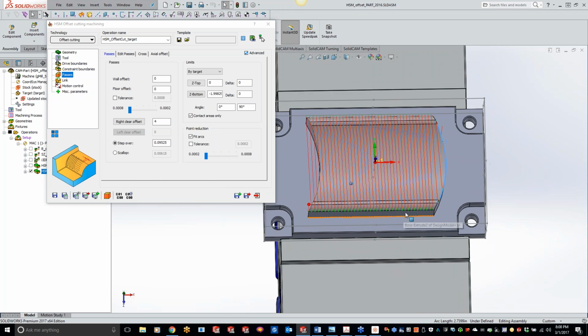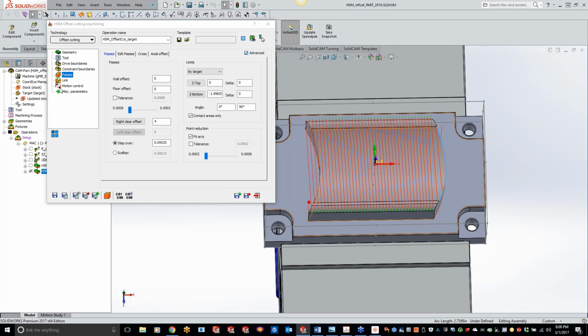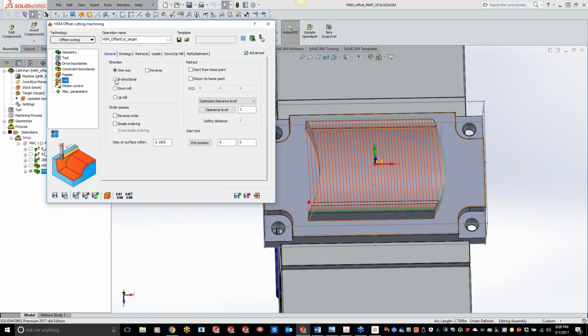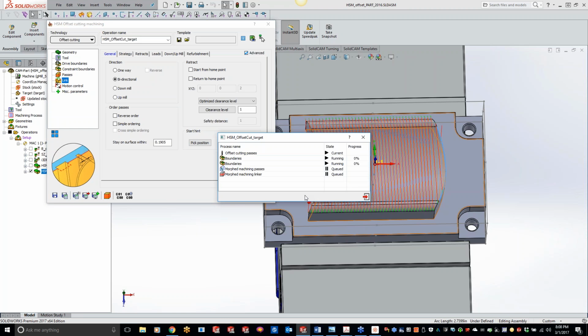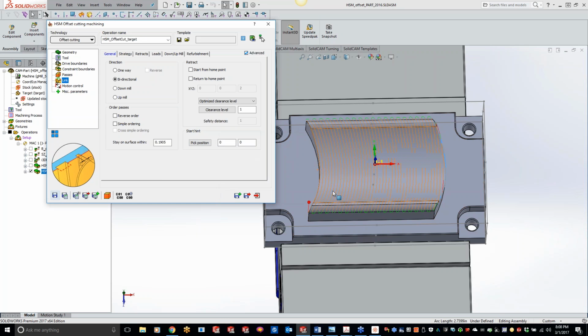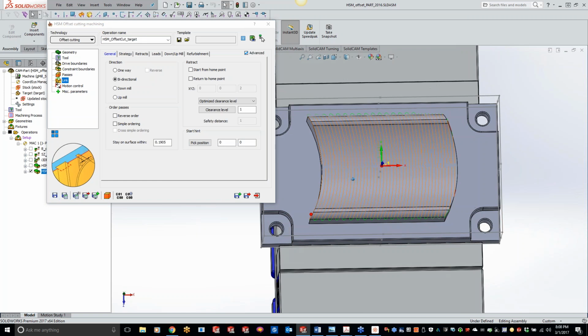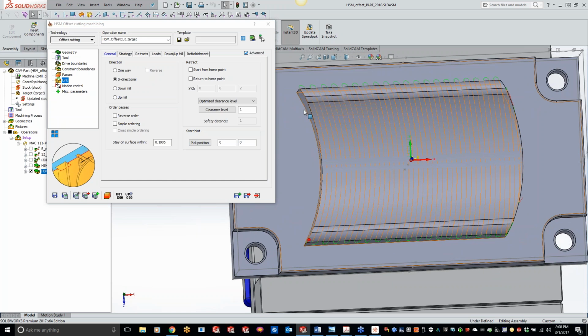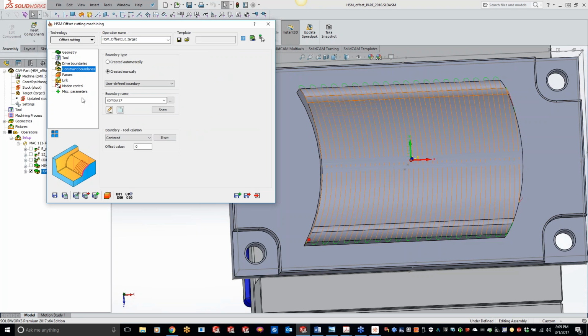It's a little tough to see with the links in there, so let me clean that up and we'll just do a bidirectional. I'm going to go to my passes, turn on bidirectional, basically doing a zigzag pattern. And now we have some nice clean toolpath, just doing nice loops going all the way around. If I get a top-down picture of what's going on here, my toolpath is actually following that guide curve we told it. We told it to start over here, move to the right all the way up to this endpoint right here, staying within the constraint boundary box that I'd chosen.